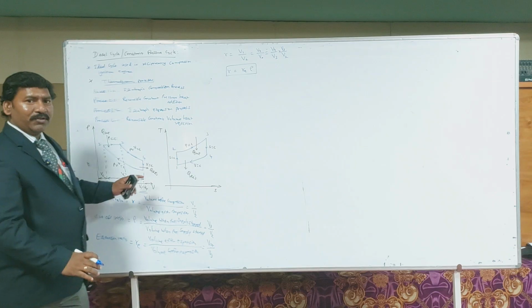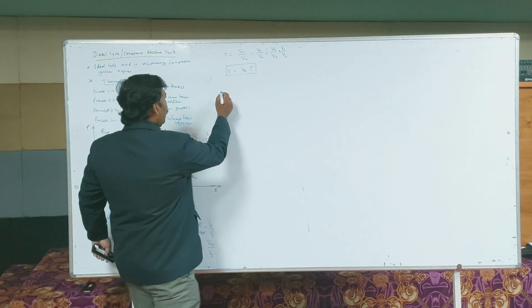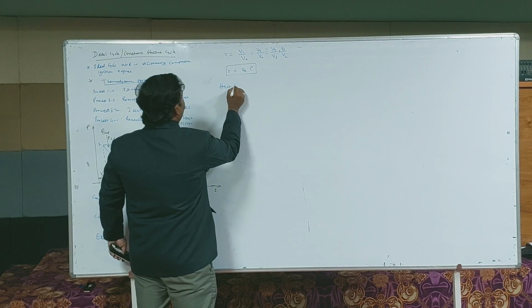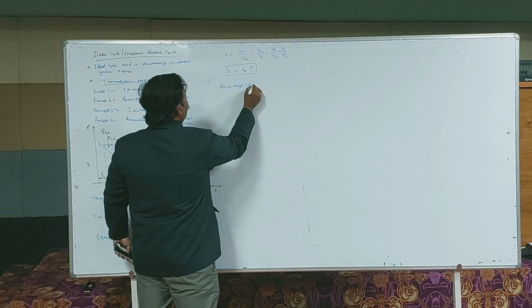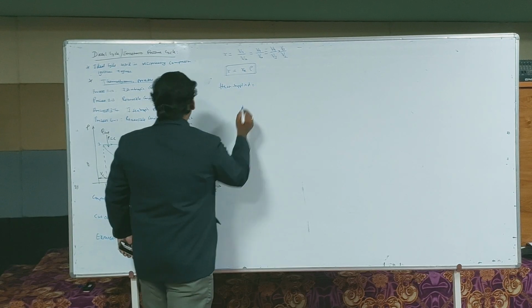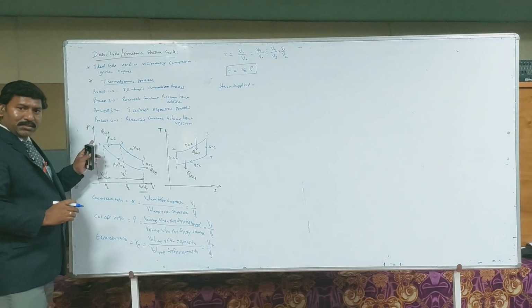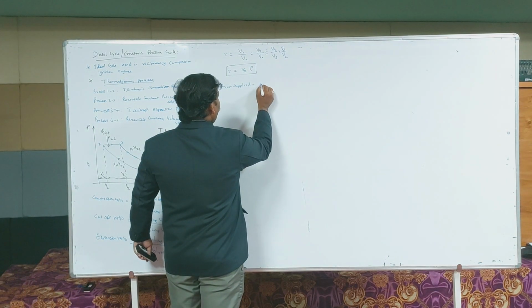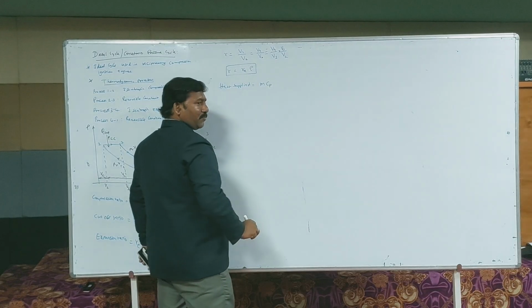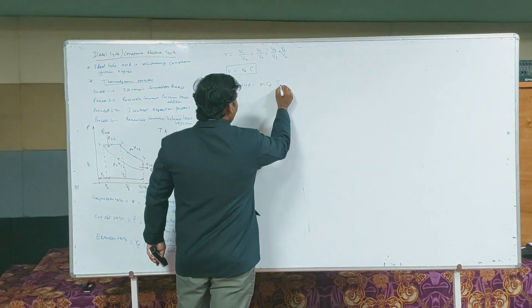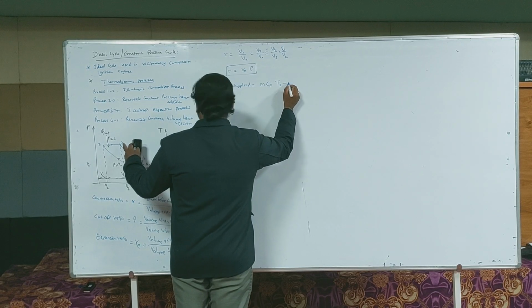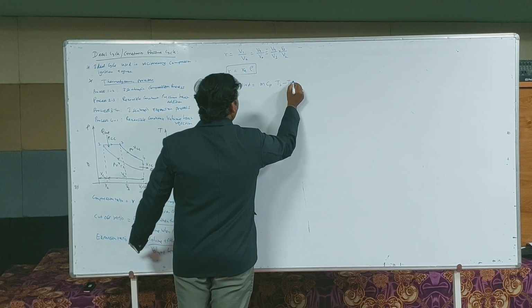To start with the efficiency of a diesel cycle, we have to develop a relationship or correlation for the heat supplied. So heat supplied is at constant pressure process. For a constant pressure process, the heat supplied is equal to m into Cp into, after the heat addition the state is 3, therefore T3, before heat addition the state is 2, therefore T2.